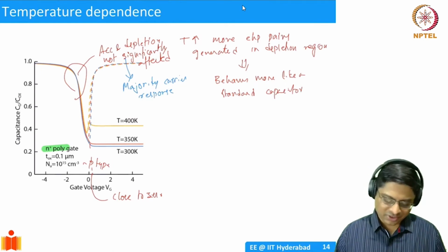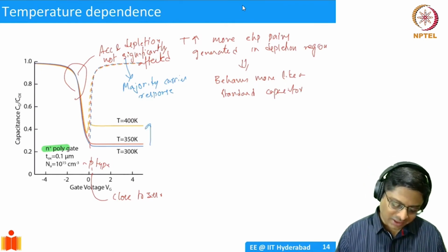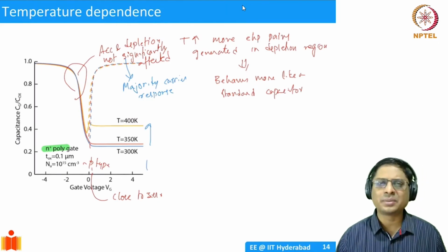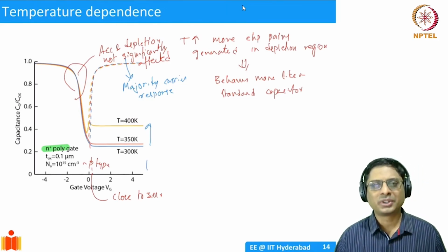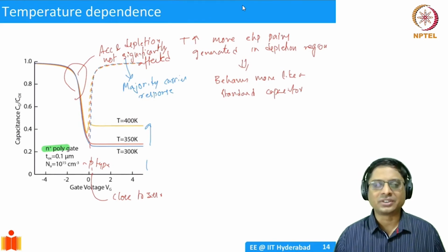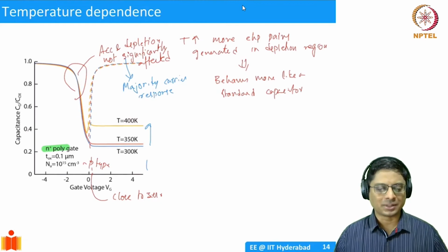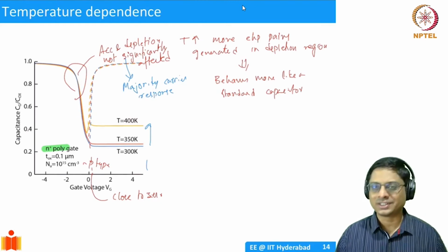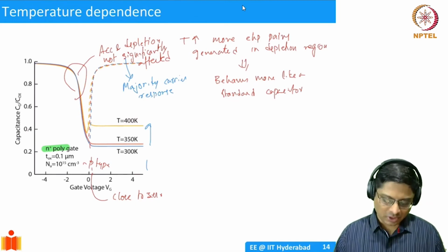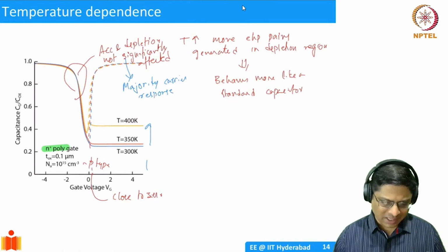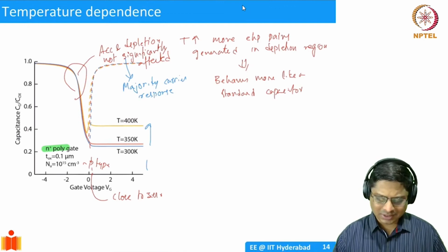Okay, this is how the temperature changes. So you see that as you go to higher and higher temperatures, there is a very significant increase in the minority carriers. So that tends to screw up your devices. Okay. So that's why electronic devices, whenever they get heated, it's not good for their lifetime. They get spoiled much faster. So whenever your laptop or computer is getting heated up aggressively, then you have to really think about what's happening, and it might actually be approaching the end of its life. Okay. All right. So this was the parameter dependence that I wanted to talk about.